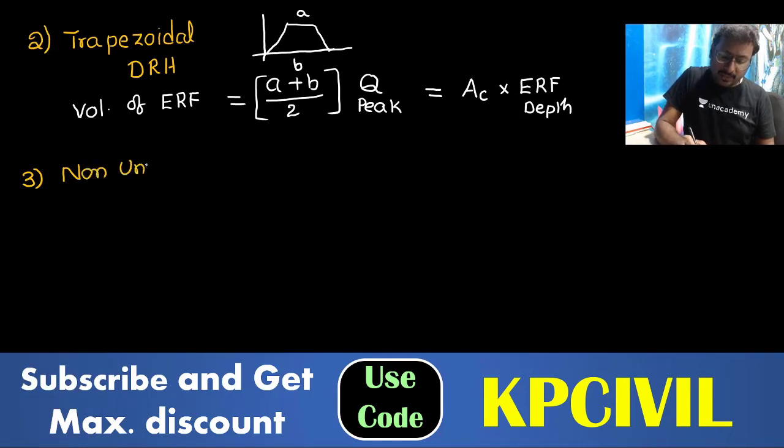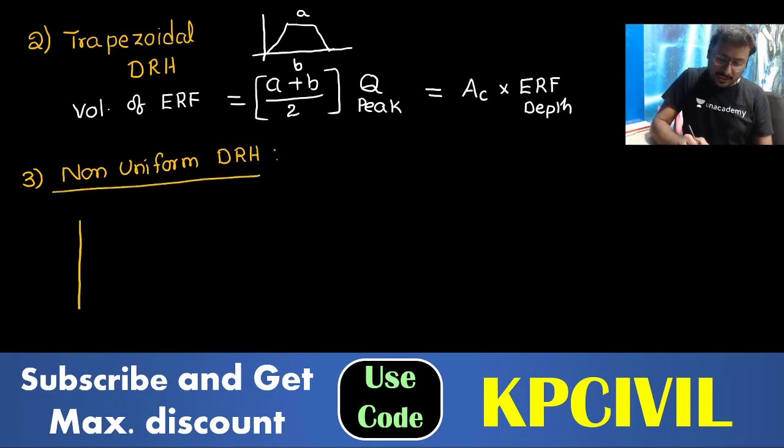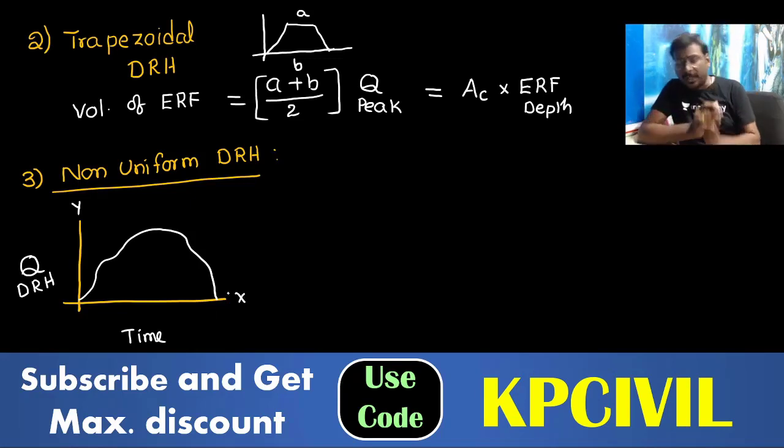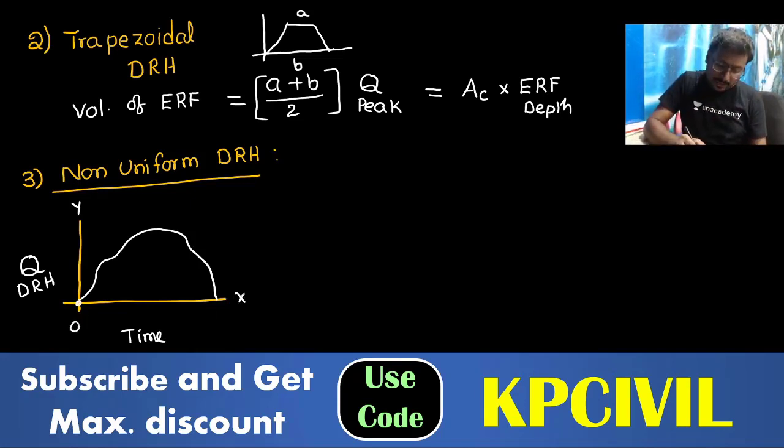Non-uniform direct runoff hydrograph, an irregularly shaped DRH. What is the non-uniform DRH going to have? This is the graph we are going to consider, so it may carry a shape like this. DRH discharge on the y-axis, time on the x-axis. The final formula, after we have applied trapezoidal integration and taken Q0 and Qn out, since Q0 and Qn are 0. Final formula I am writing.